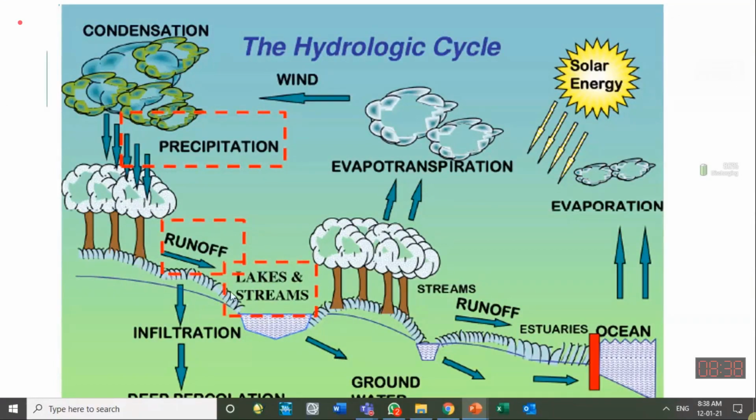Here we are showing you the ground surface line, grassy land or ground. Underneath, a few meters or a few feet below the ground surface, usually we have the groundwater surface, and we call it the water table. Between these two, the ground surface and the water table, we have the soil layer, which is not fully saturated. Not fully saturated means not all pores in the soil are filled with water.